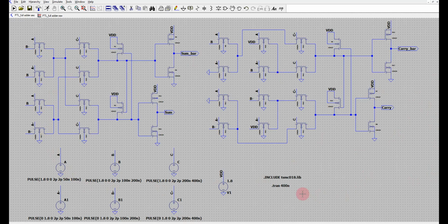Okay, now we have learned a little bit about pass transistor logic. In the same manner, I have demonstrated how to implement a full adder. You can go ahead and design multiplexers, and mux based circuits, because for mux also you can go through the literature, you will find several circuits where mux can be easily implemented using pass transistor switches, and decoders. So you can try out a few circuits based on mux and decoders. In case you have any problem or if you are getting stuck, feel free to get in touch with me. Okay, thanks a lot.